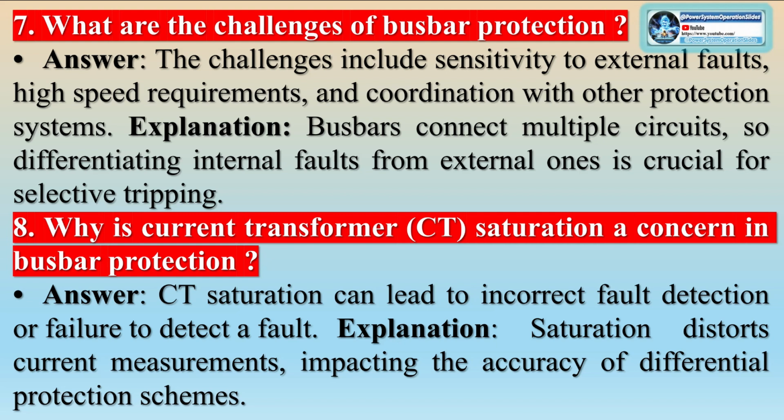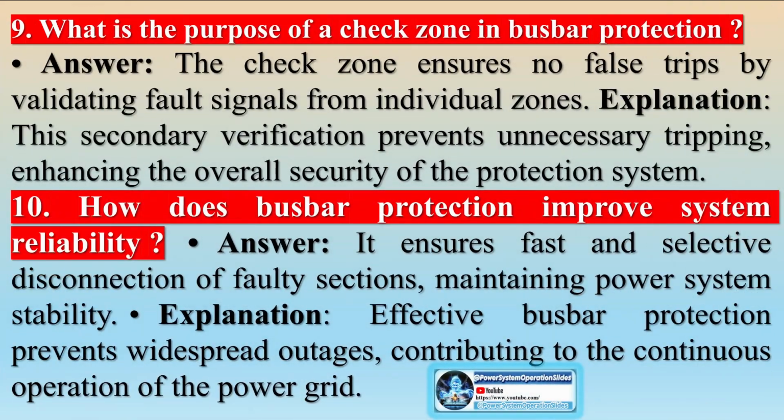Contingency arrangement in case of BBP failure. Historically, busbar protection systems used a 2 out of 2 scheme, requiring both check and discriminating zones to operate for tripping. With the advent of numerical busbar protections, this requirement has been relaxed, allowing single units to be installed on a single CT per circuit. However, if a distributed unit or the central unit fails, the entire busbar protection for one or more sections is lost, potentially taking many circuits out of service until repairs are made.